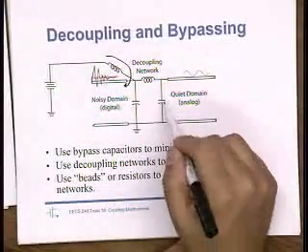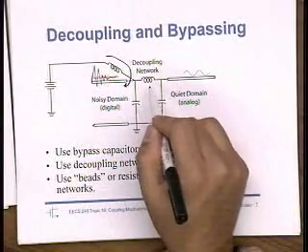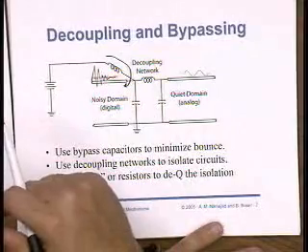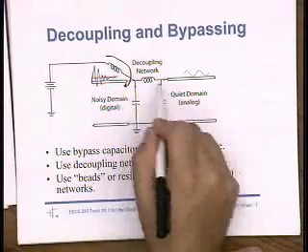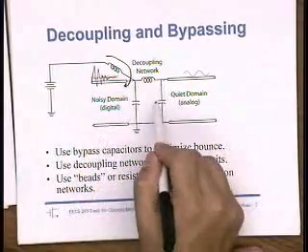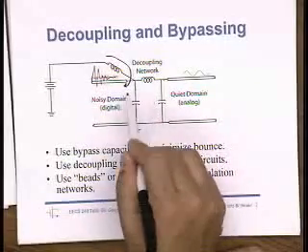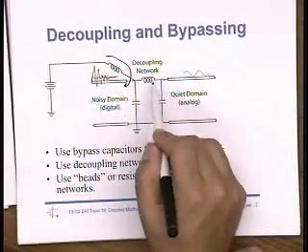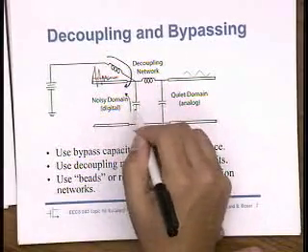Last lecture we talked about having a separate analog supply with its own decoupling capacitor, but ultimately, in many applications, you have to share the same supply. This might be the same battery. Your cell phone only has one battery. So at some point, unfortunately, you have to connect these two things together. If we just connect them without this inductor here, then this capacitor will also act like a decoupling capacitor, and it'll help draw lower frequency current into the digital domain and increase the bounce on the analog supply. So the idea of this decoupling network is to put an inductor here so that now high frequency current only comes from this capacitor, and this current is mostly a DC current.